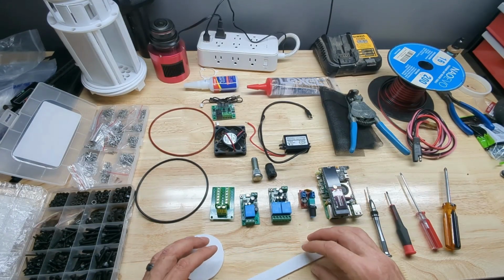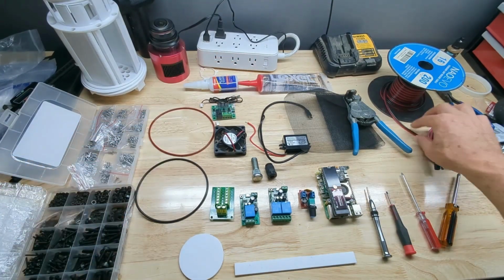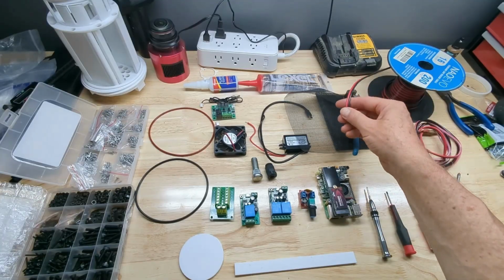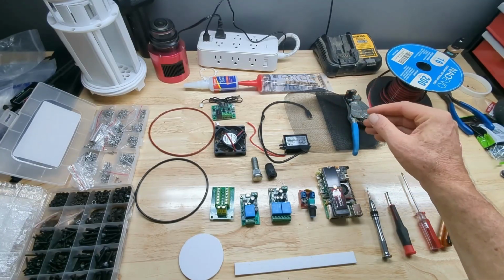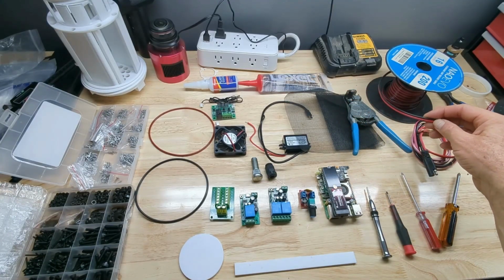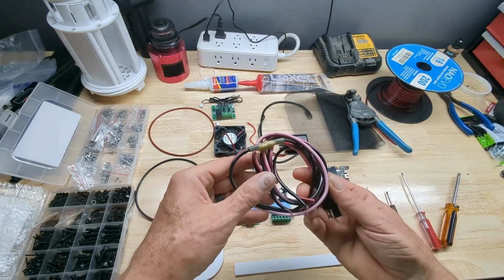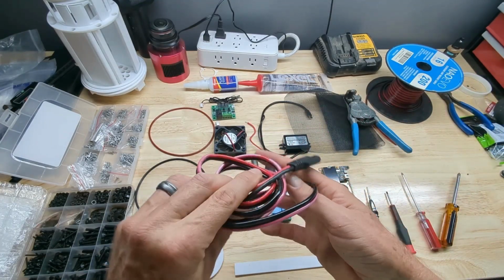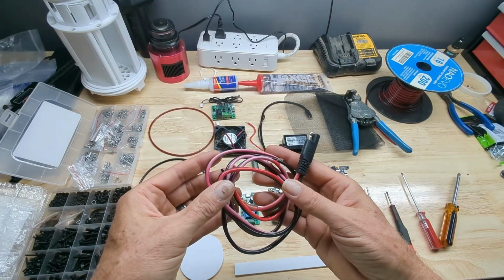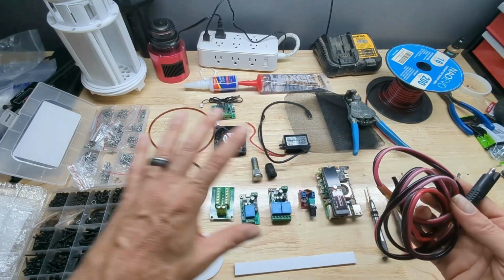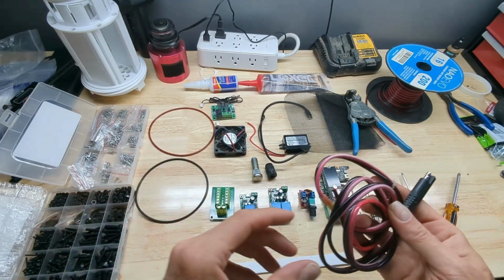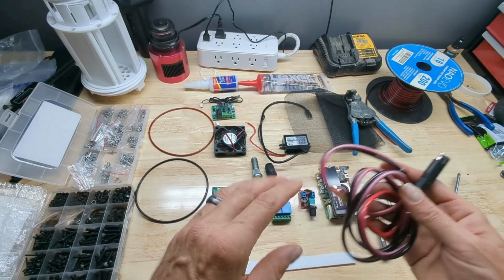Let's see, other components, the wire that we'll use. Since all the internal wiring is a very short run, 16 gauge is more than adequate. You could actually go with an 18 gauge if you wanted a thinner wire to work with. This is our power cord that we're going to use. Now, my observatory is an off-grid observatory, so everything runs off 12 volts. All the components that you see here are also 12 volts, so a 12 volt system just natively supports this.